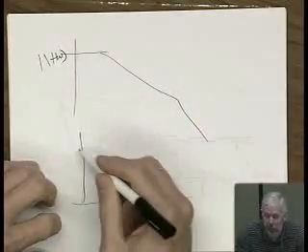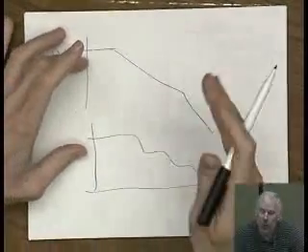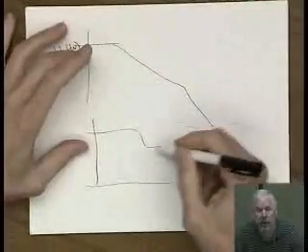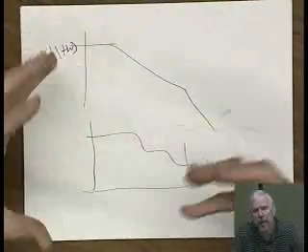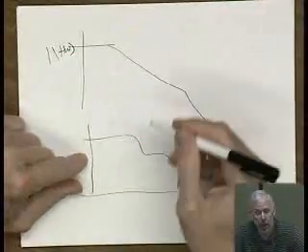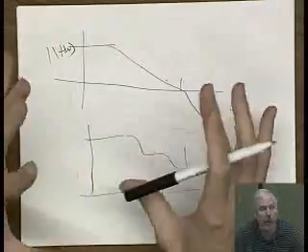Look at those phase plots and see what's going on. So the Bode plots: look at the whole Bode plot. We have a test bench for you that calculates the phase margin, which is just to help you out a little bit. What you really want to look at is exactly the magnitude and phase plots and what's going on at gain equals 1. See how much phase margin you have.